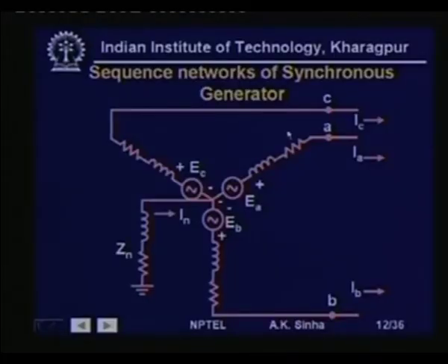Now, if we see the three phase currents flowing in these windings, which are 120-degree displaced from each other in space, will be having the same magnitude and same phase angle. Therefore, the sum of the MMF produced by them is going to be 0 in the air gap.